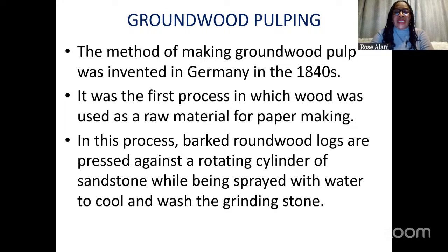So in this process, the barked wood logs are pressed against a rotating cylinder of sandstone, like what I showed you before, that have different cutting patterns. While spraying with water to cool and wash the grinding stone so that it will still remain good for subsequent grinding, keep on grinding and washing it. Then after some time, you sharpen it again.